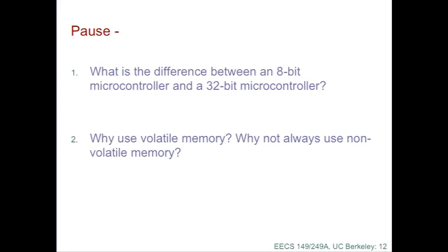Yeah, that's one big one: flash memory will wear out after a while. Okay, so DRAM doesn't wear out. Well, probably does. You get electromigration, but it takes a really long time to wear out. Yes? Volatile memory is also faster to access, especially static RAM. So don't get confused. Why is static RAM called static if it's volatile? No refresh, right? So there are different levels of volatility. Volatile means if you take away the power, it forgets everything, okay?